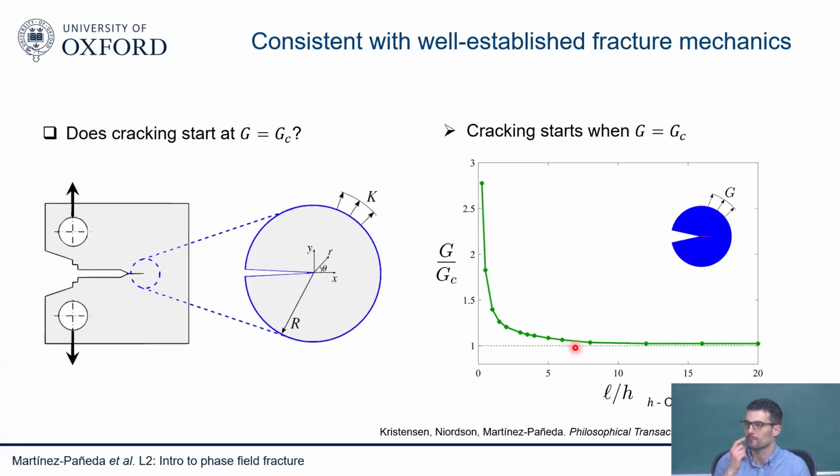Yeah. This curve, is it sensitive to the type of material? Or will it change if I use steel or glass? No, it's roughly the same. It's normalized, so it only relies on Young's modulus, but it won't change much. So what you find in this curve you can apply everywhere. A rule of thumb that people normally take is 5 times: if you use an element size that is 5 times smaller than the length scale, you are safe.